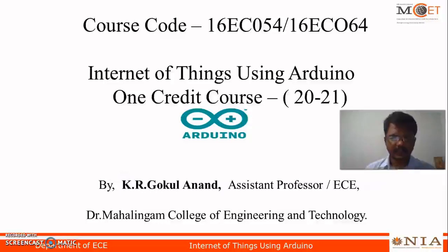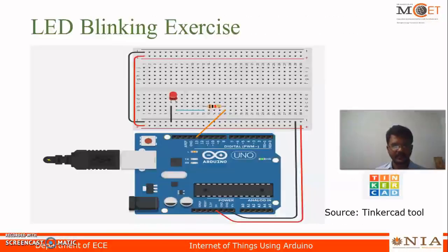Welcome back. We will start the session. In this session, you are going to blink an LED. So you can choose an Arduino board. The Arduino board has beautiful wiring setups. So you just take the 5 volt supply and ground and connect it to the breadboard.